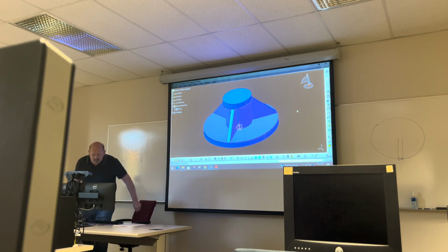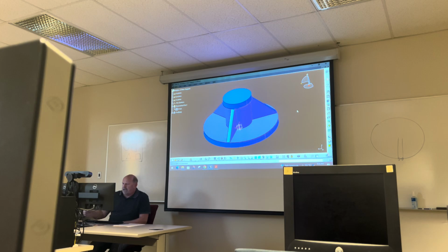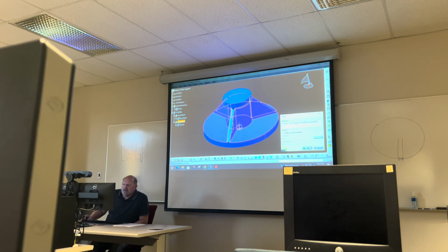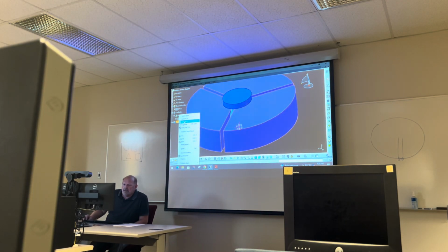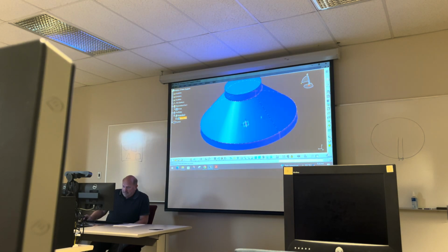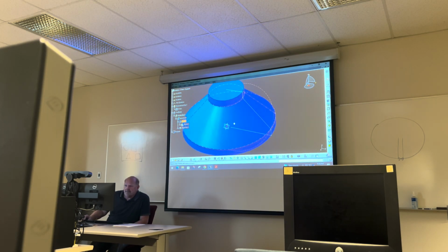And remember, if you ask what's the easiest way to construct this, well, this is my biggest body right here. If I delete this and hide that, there's the biggest body. Now, one trick on this is, once you build this shape, before you go out of it, you have to put two fillets on here, one here and one here, and I'll show you why. So there's the shape, right?